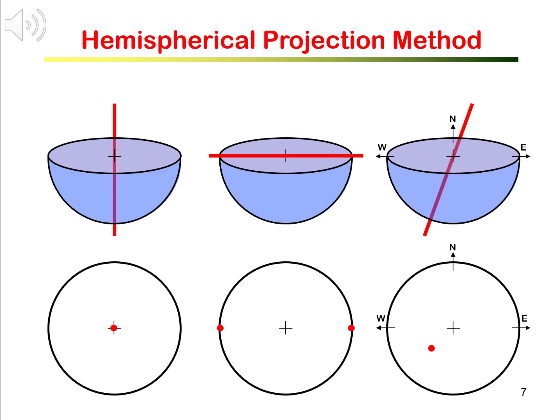The inclined line will make a mark on the hemisphere. The location of the mark is governed by the trend and the plunge of the line. By projection, the mark becomes a point on the plane. A steep line will be represented by a point closer to the center.